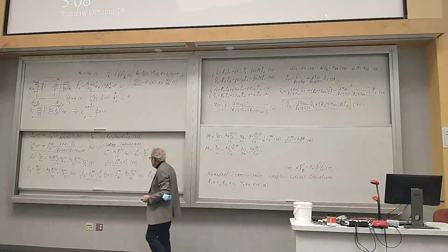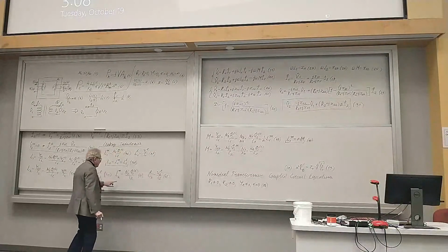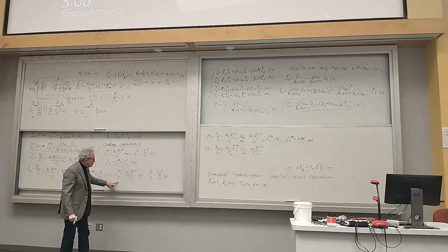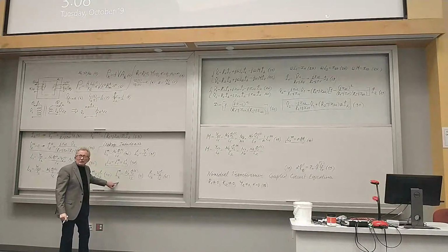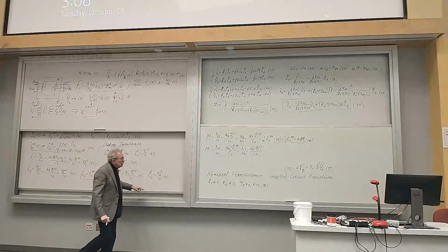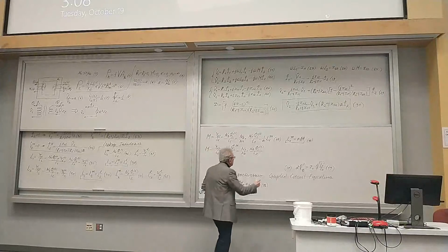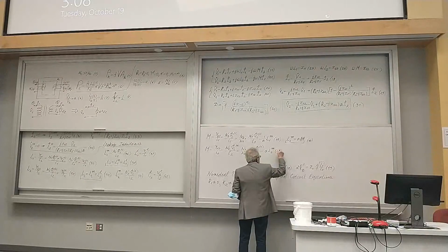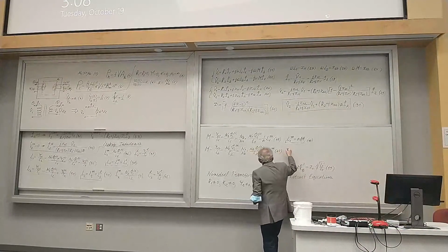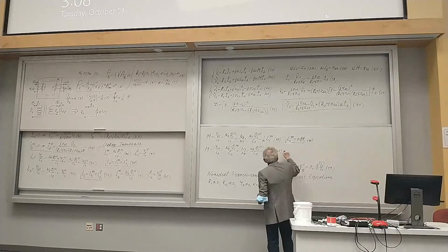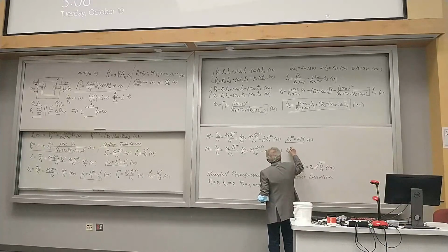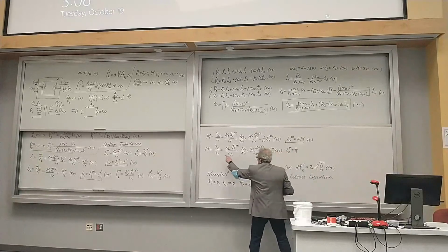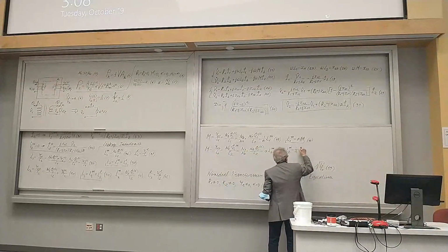And then I will go to this formula. So the second term, you can see, is nothing else but the main secondary inductance. And this is the turn ratio. And from here I can find what the secondary main inductance will be. It will be 1 over a, so I divide by a, times the mutual inductance.